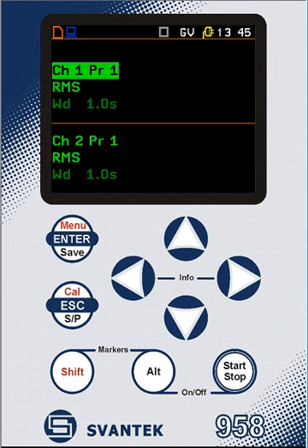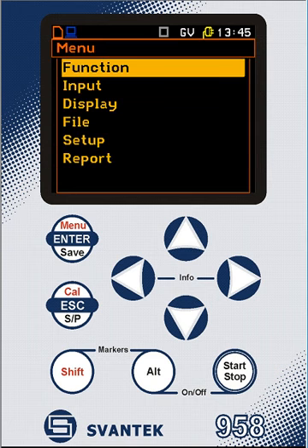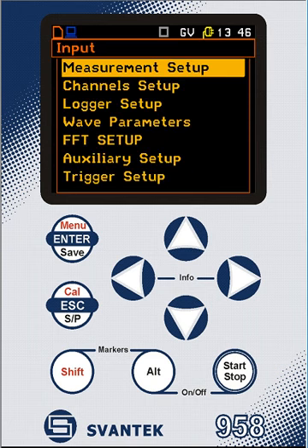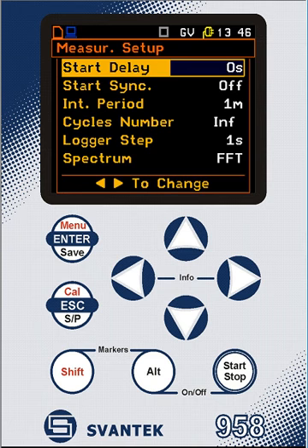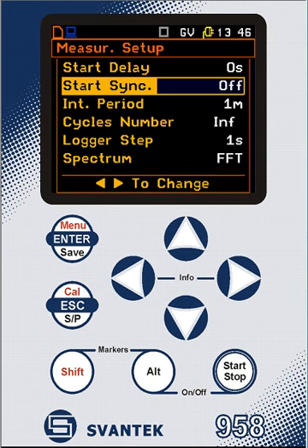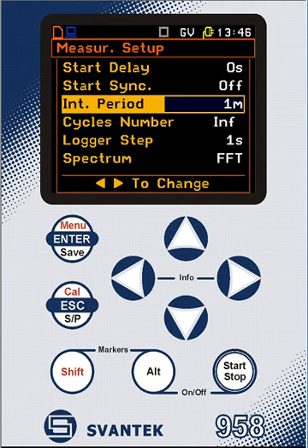of the analyzer and set up our measurement. The first part is the timing of the measurement, if you like. Here you can put in the integration period for your background vibration measurements. Now, BS7385 says we need to log measurements of vibration continuously to ensure that they don't exceed particular levels.